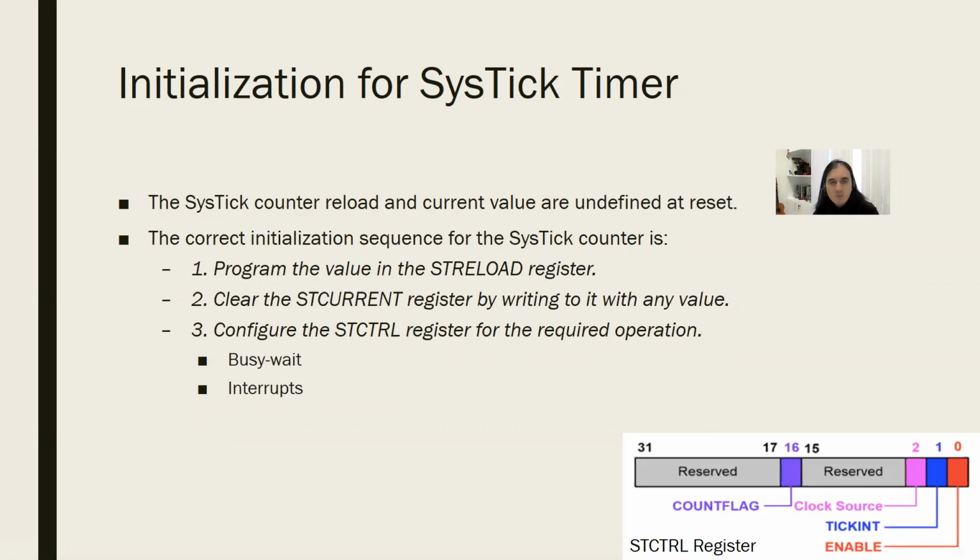The first one will be a timer initialization, in which we will not be using interrupts because we are going to make this bit 0. So to make this bit 0, we'll need to put some necessary values in some necessary registers.